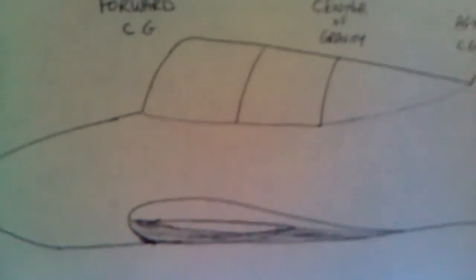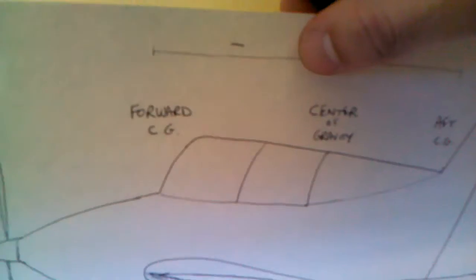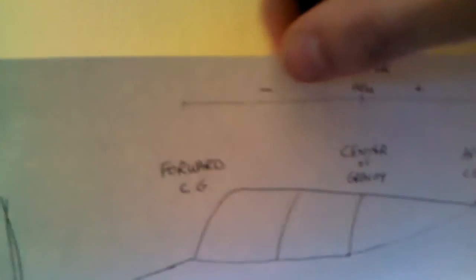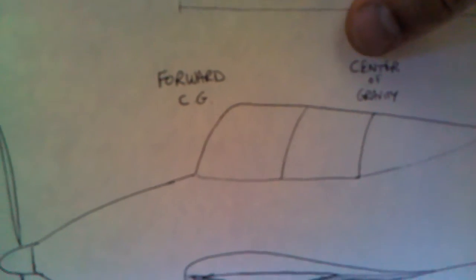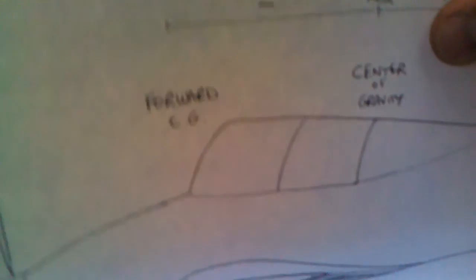So let's say that the total weight that this airplane can uphold is, let's say, 100 pounds of cargo. It's a real small airplane. It makes a big difference where we put that weight. If we distribute it to where it's within a certain range, because you have to be able to fly with just two people up front, or enough to be able to have some baggage in the back. So there has to be a little bit of a range. It's not always going to be perfect. But the point is to not have it too far forward or back of that range. And there are a couple of points that we can go over as far as the characteristics of that.